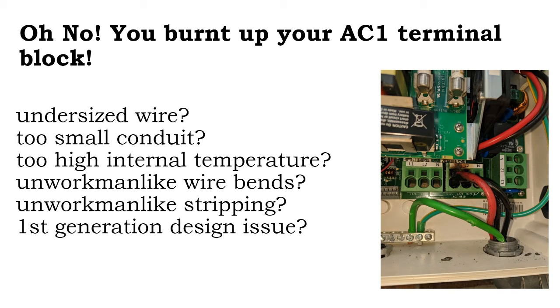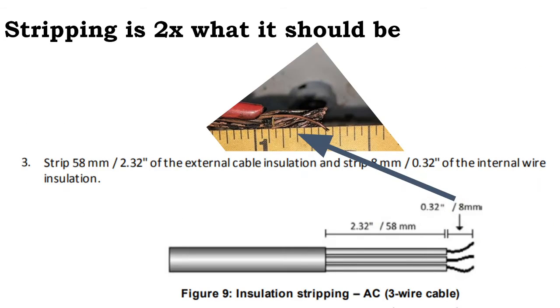Or is it more likely a design issue? Did they use... it's a first generation product. Maybe their terminal blocks are too cheap. Usually it's a workmanship issue. In this case, the installer did not strip the cable jacket off according to the manufacturer spec.